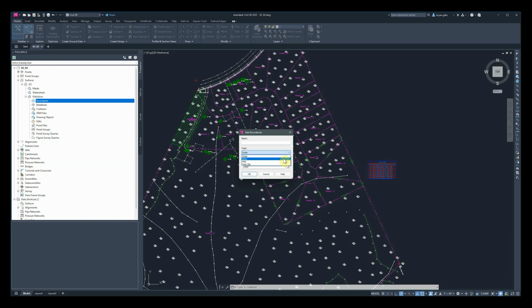The idea here is to try to create a viewport or a view frame that we're going to focus on, and we're just going to look at that study area. Hide is essentially the opposite of that. It's going to create a hole within that reference block or that frame that you create, and it's only going to show our triangles outside of it.